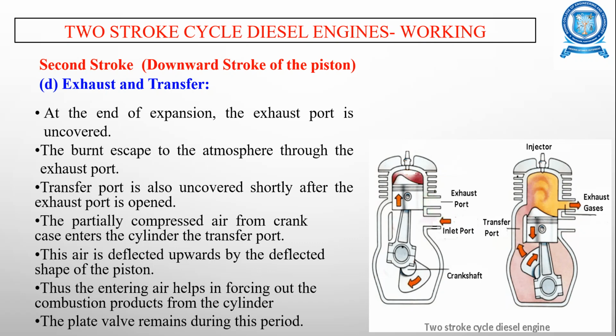The burned gases escape to the atmosphere through this exhaust port, as you can see from the second figure. The transfer port is also uncovered, so the partially compressed air from the crankcase enters this cylinder through the transfer port.